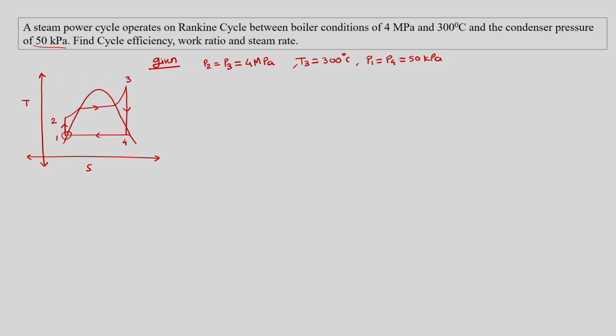So steam table we had discussed that there would be different sections, and initially we would have a section where based upon the saturation temperature we can find out the enthalpy, entropy, internal energy, specific volume. In other section we had seen that we can find out the same parameters based on the saturation pressure. But after these two sections there will be superheated section where we would be given with saturation pressure and different superheat temperatures. For each case the same parameters such as entropy, internal energy, specific volume would be mentioned.